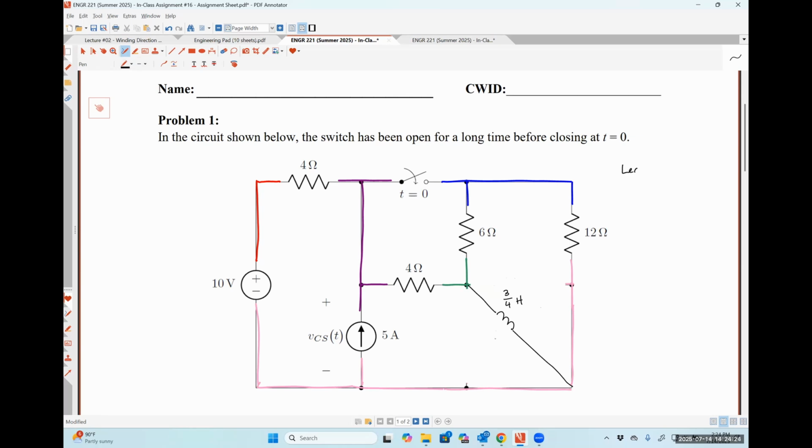And for what it's worth, we've accidentally jumped forward and found what LEQ is for step number 4. Okay. So I've made that simplification, and I intentionally didn't ask what was going on with either individual inductor because there's really not a good way to determine how any current is going to split between those two inductors when we're at DC. Later on, when we're dealing with sinusoidally excited circuits and what's called impedances, we can just use current division relationships to figure out what's going on.